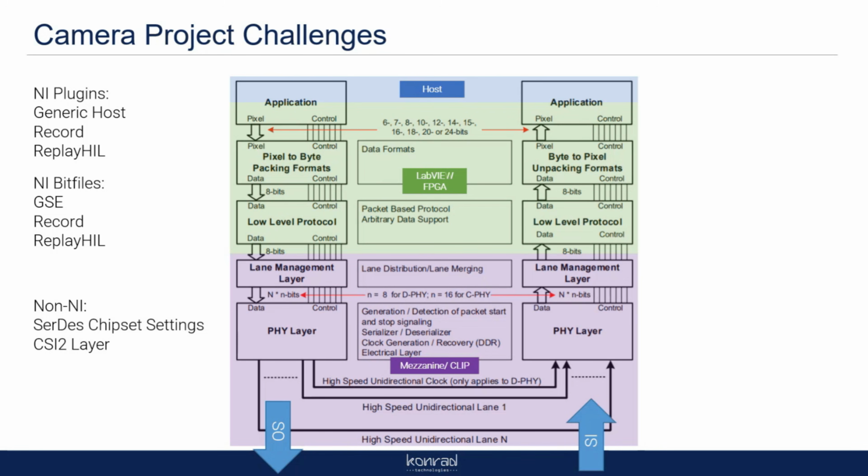It's amazing to me how quickly we fill up PXI chassis. It's like, oh, okay, never mind. Got to delete that test data. So that 45 seconds is going to be overlapped, because you have to start the next recording before you finish the first one, because you have to save it. Then you've got to piece it back together again, and that's where your synchronization comes in.